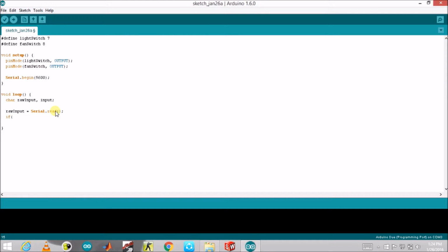So now what I'm going to do is filter the unnecessary values that I get: input not equal to 255. Sometimes, depending on your Arduino board, this 255 value may vary. So I suggest that you verify once, but that value will be a constant every time. Just check it for your board. If you are using an Uno, it's 99% 255. If it's any other board, I suggest that you go and check that value. Now I've taken my input, so it will only initialize if the value is not 255.